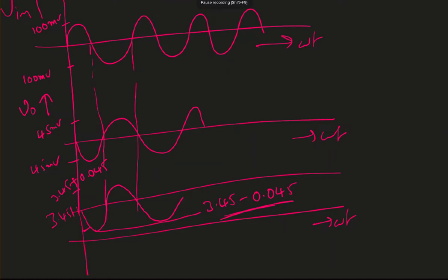Okay, I'll stop this video here. As mentioned, you can solve any example by using the T model. But while doing AC analysis, if the source is grounded, then you can use the pi model. The pi model is easy to solve. So if AC is grounded, use the pi model. I will stop it here. In the next example, I'll try to solve a pi model. Thank you.